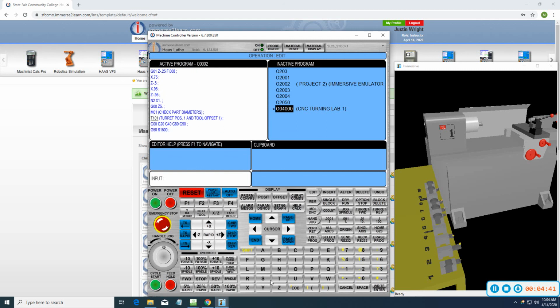Same thing. Tool 2, offset 2, and Alter. Now, I'm going to keep arrowing down because what I had for 4 as a part-off tool, this machine has set up as tool 1. So alter that. So I've done all of my altering that I need for my program. I just changed those two tool numbers.